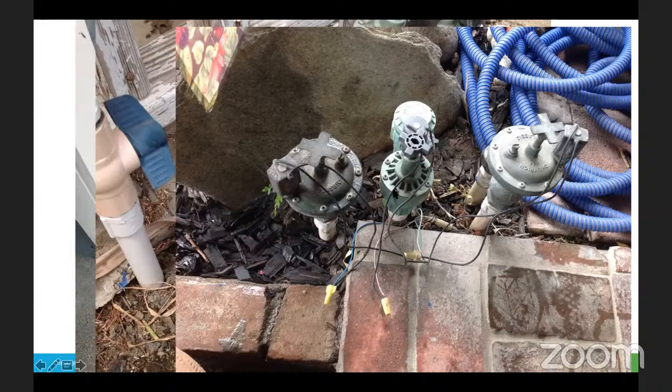So there are certain things to think about. A smaller valve will give less water to the zone. If the zone needed more water, let's say there were more sprinklers on the line because they had a larger valve, now the system won't be operating as efficiently. So things to think about. You always want to replace what was there. So if this valve went out, instead of replacing it with something different, if possible, go with the same one.